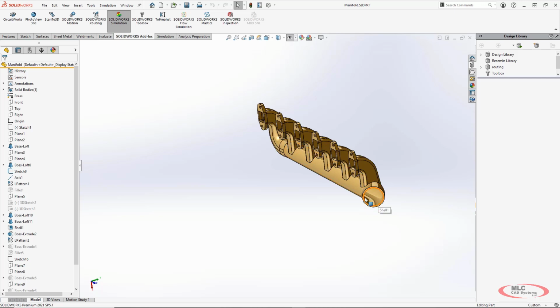So this is our inlet over here on the right. And then for this design, we want the air to be relatively the same going through each of these valves. So we're going to use flow simulation to determine this. To set up a study, it can go pretty quick and it is intuitive, especially after a little bit of training, just like SOLIDWORKS simulation.